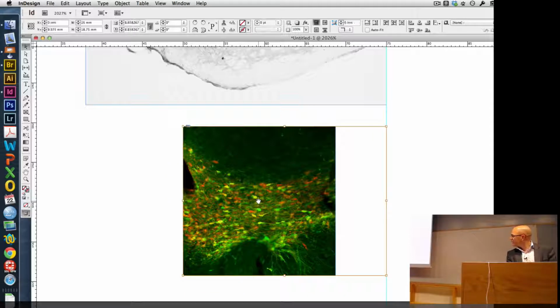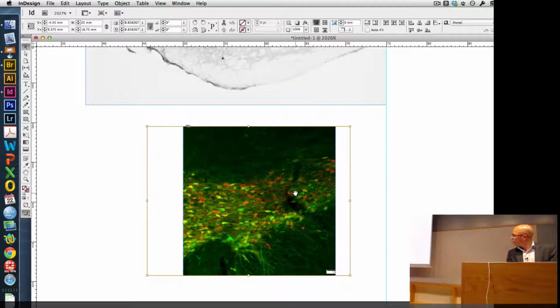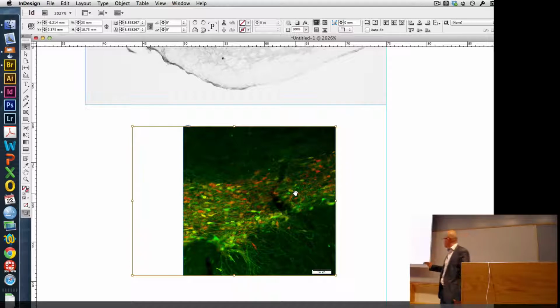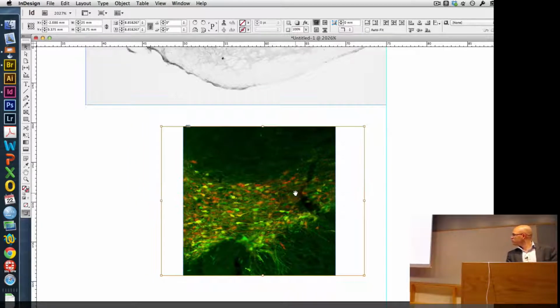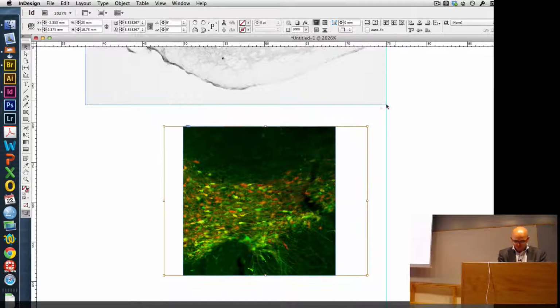If you click inside that, you now see the red outer line, and that is your full original image. So you can either use the hand and drag this image around inside, or use the arrow keys, so you can choose yourself to move this. And here you see this example of why it's not good to have a burnt-in scale bar. This image has a burnt-in scale bar here, and now I'm locked to either only showing that specific part, or showing something where this is outside. So you really want to avoid that region.